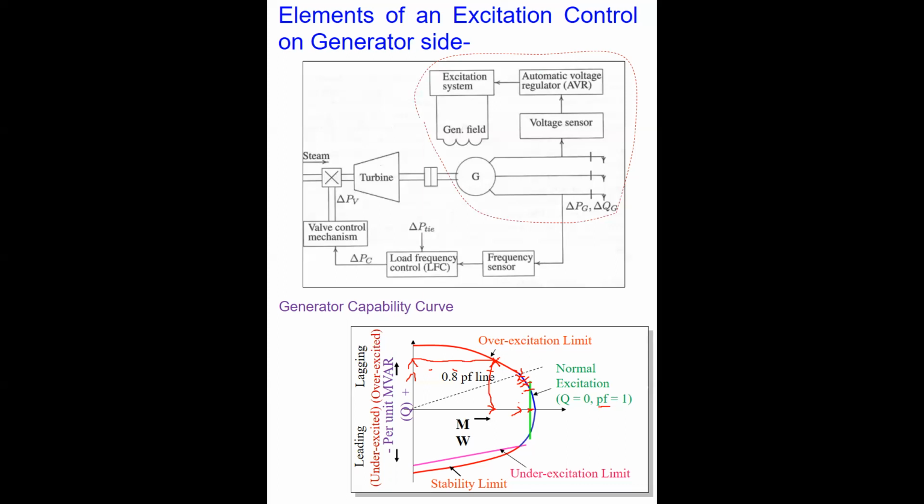But again with some proportion of reactive power as well. So it is preferred that generators should be operating in the range of 0.9 or 0.95 lagging power factor, right? So if you have 0.9 or 0.95 power factor, then you will have this much amount of active power flow, and then you may have some reactive power flow here. So with 0.9 or 0.95 lagging power factor, right?